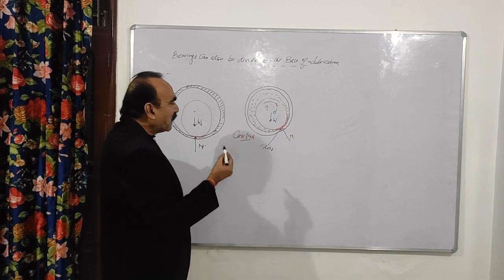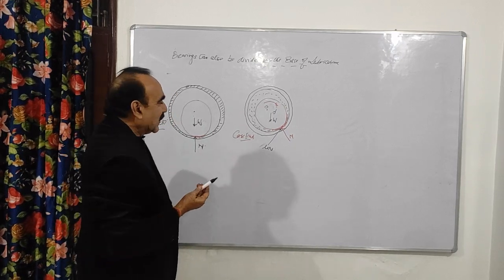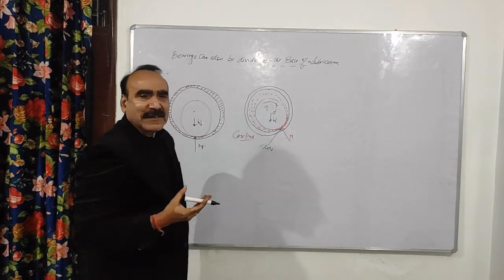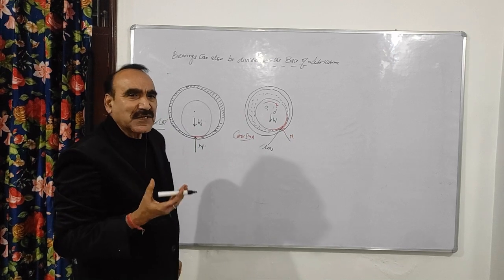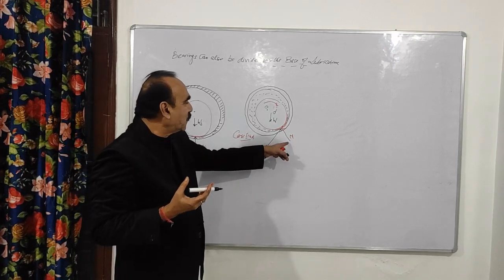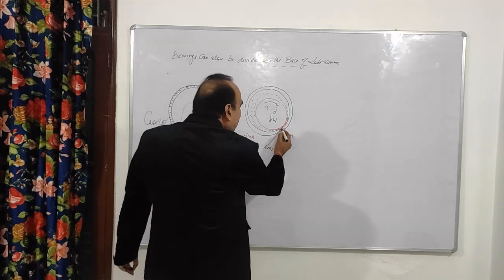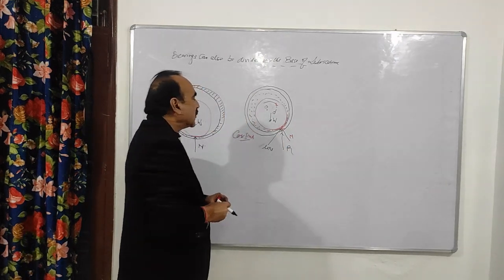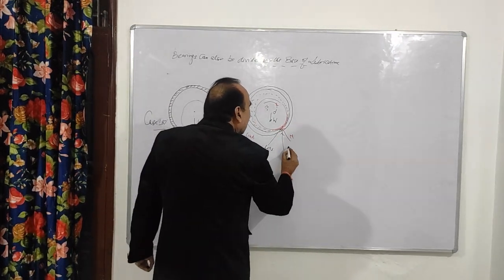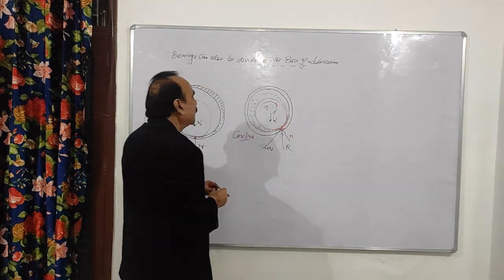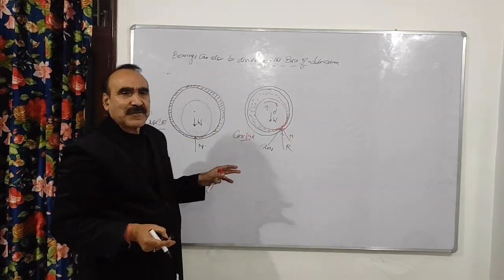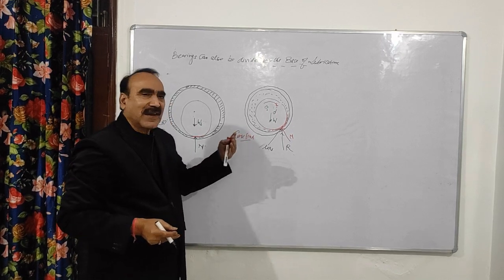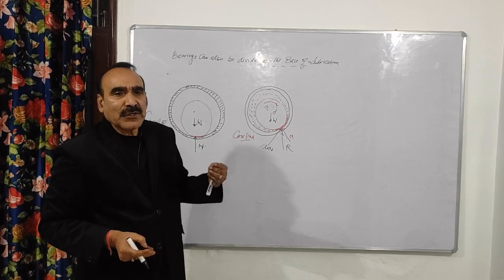Now, if I take the resultant of this, definitely this load has to be supported by some force. That force, which is the resultant of this normal force as well as the frictional force, will act like this. So this is your resultant force. So here you have seen that in this case, when it just starts rotating, this is the second case when the shaft just starts rotating, right?